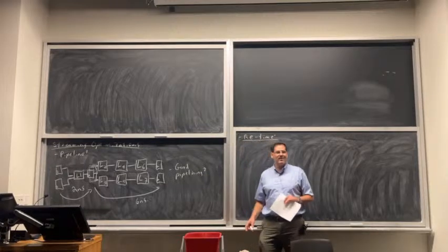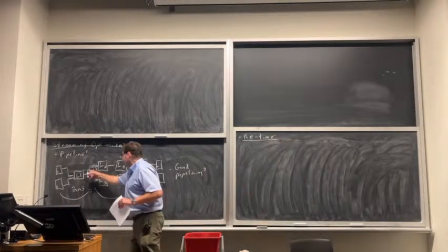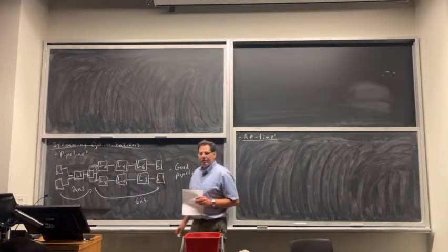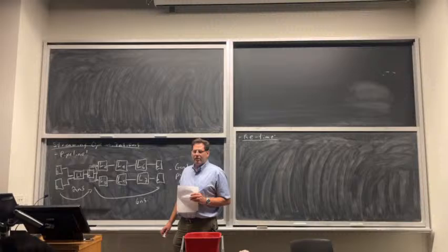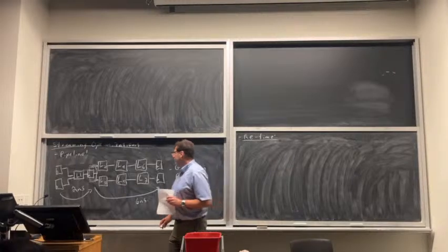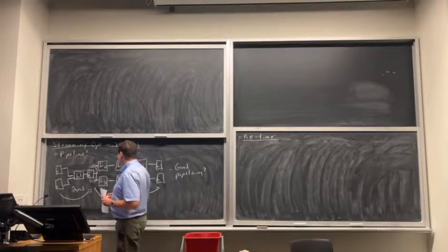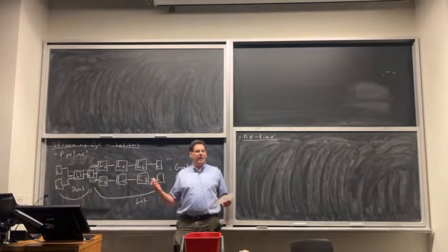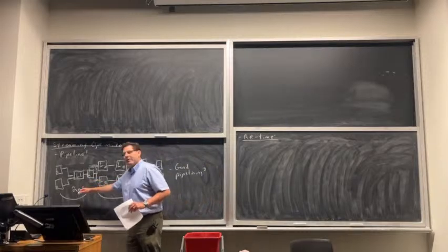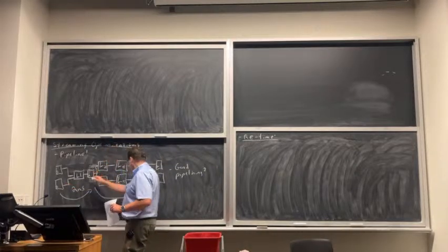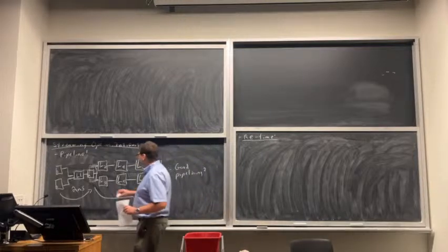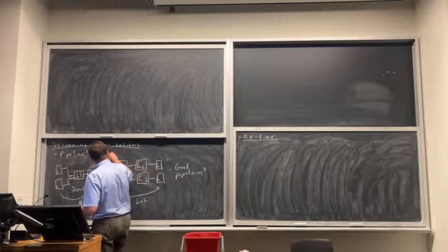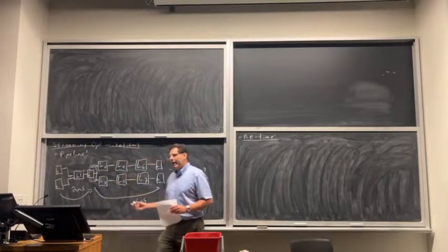Okay, so what does retiming do? Can you tell me what retiming does? It will move registers around to balance path delays. So we didn't like this because our path delays are unbalanced: 2 nanoseconds on the input side of this register and 6 on the output. We have to take the worst case as our delay. We'd like to move this register over here to this spot. And if we could do that, we could actually get balanced path delays.